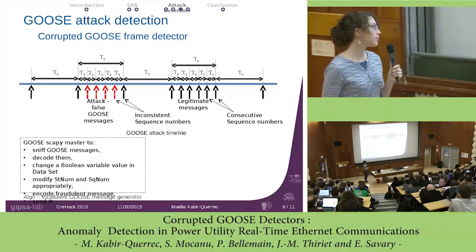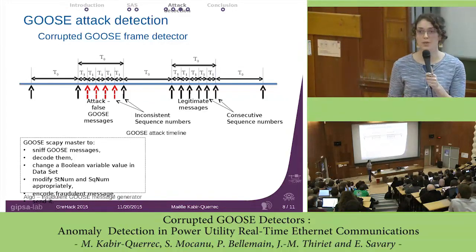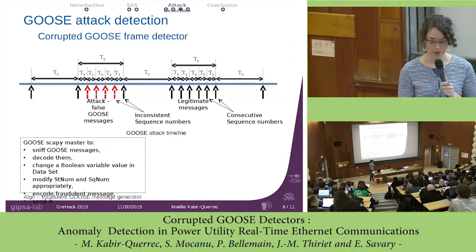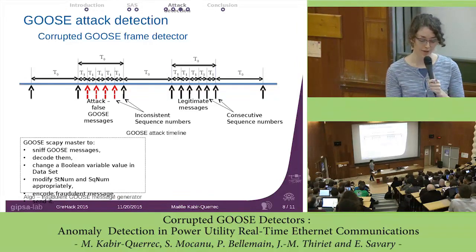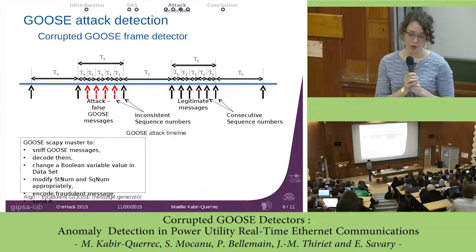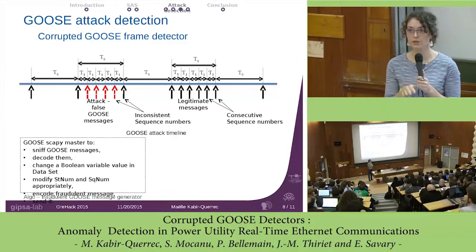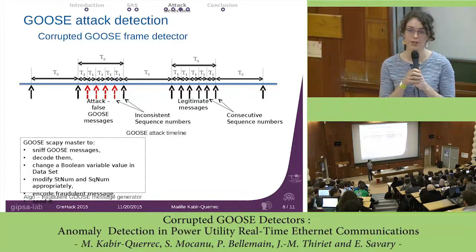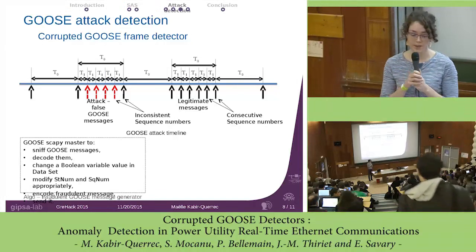So here is the algorithm of our fraudulent GOOSE messages generator. It is based on Scapy, a Python script. I didn't do it from scratch. I used some work of Hoyos, a researcher from Boulder University, and I put the reference in the paper if you are interested in getting it.